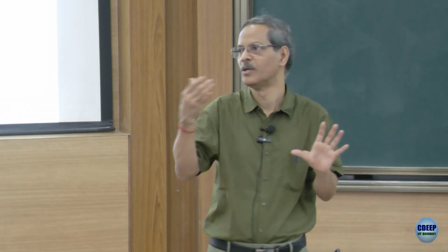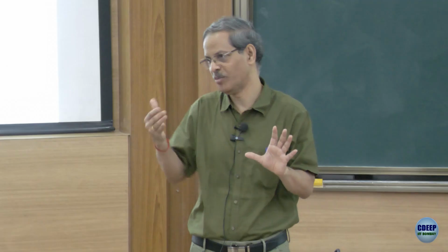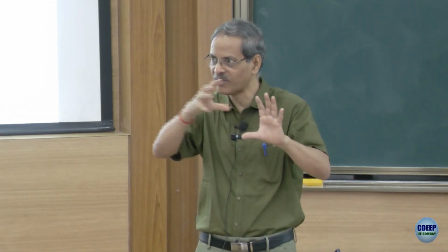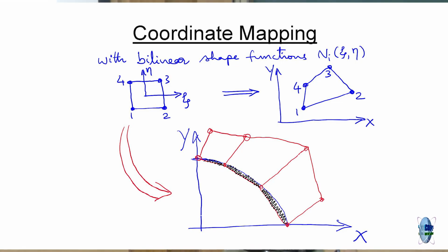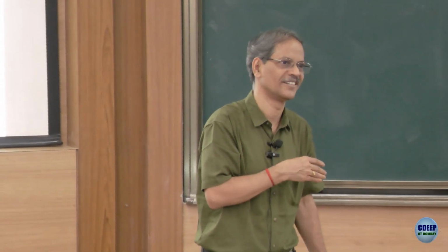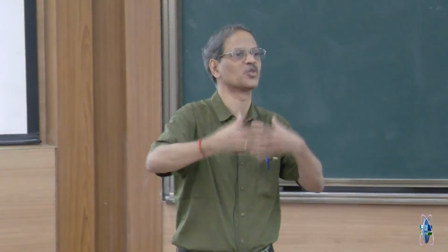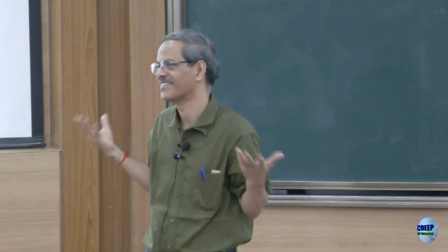If I were to do cubic element, it would be even better. So this is the P refinement model we are talking about. Yesterday's class I mentioned the possibility of doing it using H refinement. I use quad 4 element only, 4 noded quadrilateral. So linear shape function, straight edge will remain straight edge, but I would use more and more straight edge elements. So I am able to approximate the curved shape better and better and better.